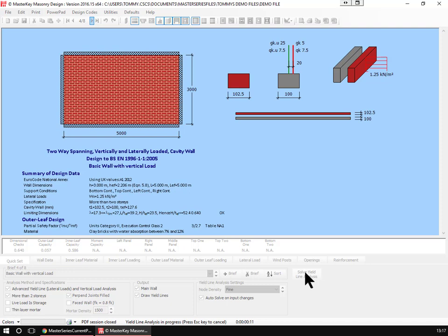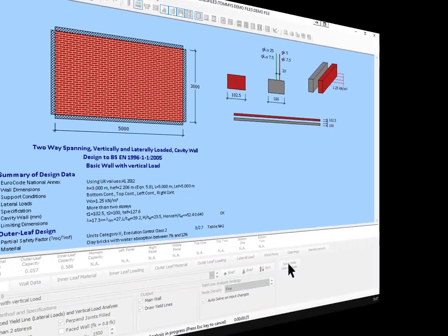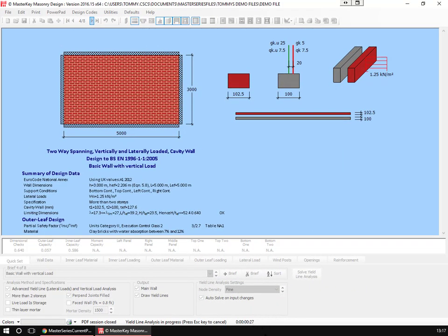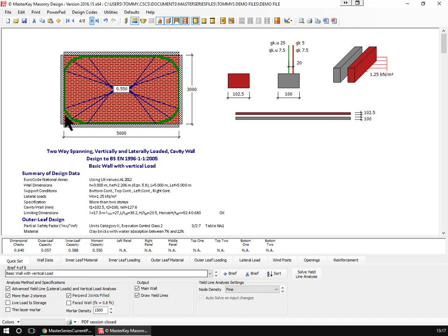10, 15 maybe seconds to do that solution of the yield lines. It's still going strong there at 26 seconds. It's listed down here at the very, very bottom. And there we go. So 0.550. If I was to turn off the yield line analysis, I would see that under the old-fashioned methods, I'm getting 0.599. So there's a reasonably close correlation there between the two sets of analysis. And I just go back and it will remember my solution there.